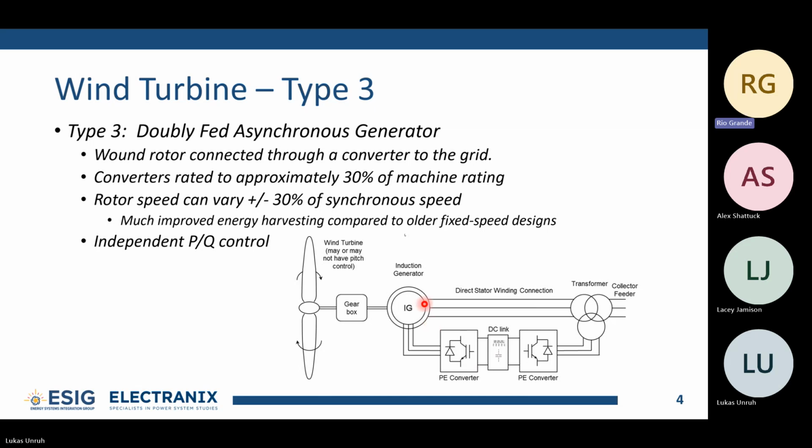And we also have this grid side converter here, which we can use to control the reactive power out of the turbine. So we have independent control over active and reactive power out of this device, which is something that you didn't have from the previous generations.